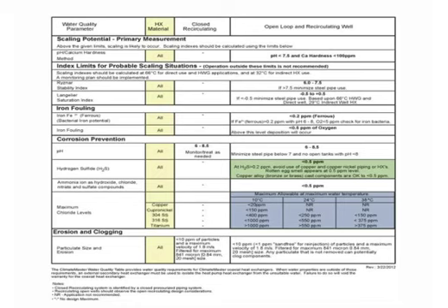Well, if you think it through, folks, you can produce 125, and in some cases even higher temperatures out of that hot water generator. So if that is the same water coming out of the well they're using in the home, and it has chloride, you may not have an issue with the heat exchanger that we're doing our heating and cooling from, but that de-superheater or hot water generator coaxial heat exchanger, you could compromise it because the chloride and temperature made it aggressive and ate through.